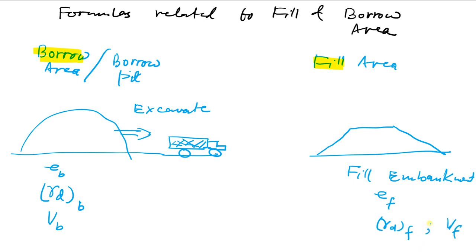So these are the basic terminologies. We excavate soil, we put it in trucks, and those trucks bring the soil, and then we use different machines to compact, and the soil is placed in layers. So in thin layers we place the soil and we keep on compacting with different machines, and we keep on rising till we reach our desired height. Okay, and we are going to see in coming lectures what equipment we use for compaction.